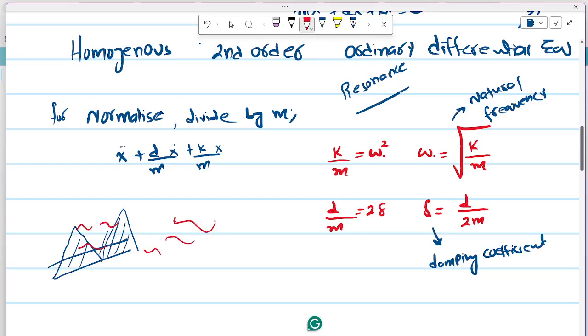If the wind is causing a certain frequency of vibration in the bridge, and that frequency comes near the fundamental frequency of the bridge, or the natural frequency, let's say it was 12 hertz, it means the bridge will start to vibrate at a very high amplitude, and ultimately it will fracture, it will fail, it will destroy the bridge.